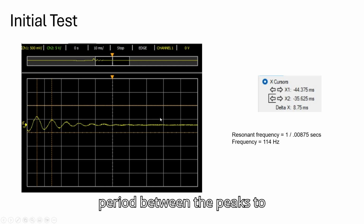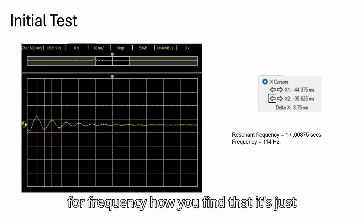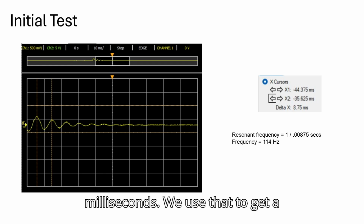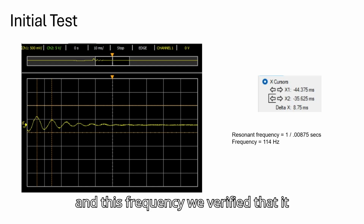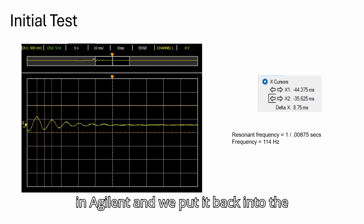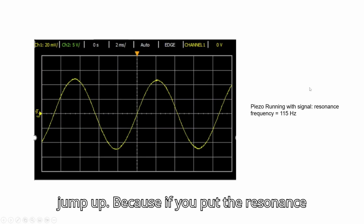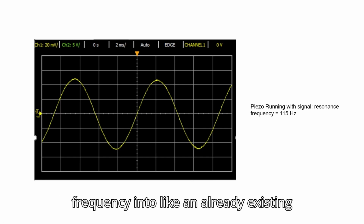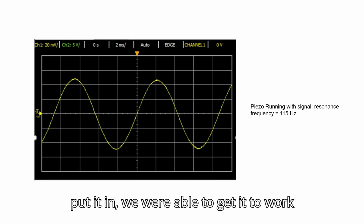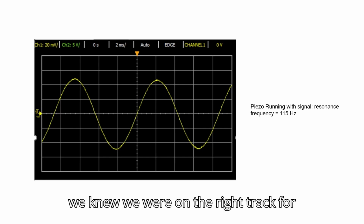And so we measured the period between the peaks to see what our frequency was, because the way you find frequency is just 1 over period. So when we found the period, which was around 8.75 milliseconds, we used that to get a frequency of 114 hertz. And we verified that it worked by putting the frequency into Agilent and feeding it back into the piezo, and we were also measuring the piezo to see whether the waveform would jump up, because if you put the resonance frequency into an already existing wave, it's the resonance if it makes the wave go up, right? So when we put it in, we were able to get it to work with a resonance of around 115, which is really close to what we had. So we knew we were on the right track for that.